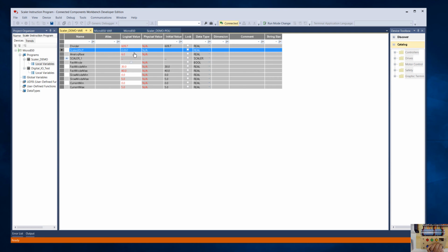I'm at 0, and as I scroll up, I'm getting to 10, about half range on my pot, which is what I would expect because I said my value should go up to 30,000 max. Instead, I'm going up to 60, but you can see once I hit that 30,000 value, the scaled output stopped increasing at 10 because I have that instruction in there that's watching it.